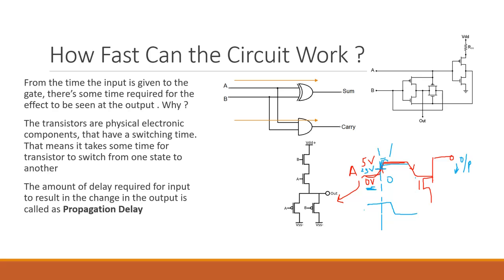Here the input is further falling down, which it might not consider, but assuming that we are only checking for the rising edges, to keep it simple, my main point is that this delay is there for each transistor. This is a fixed delay because it takes time for the transistor to understand the change in the input and then reflect it on the output.